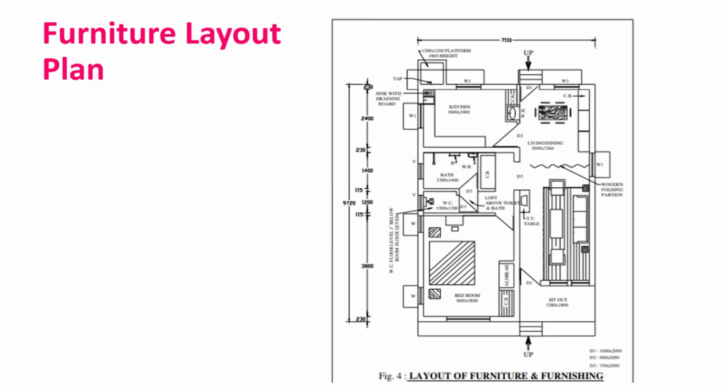Surface water drains. Again, we are required to have any type of land, passage or other area within the curtilage of the building effectively drained by a surface water drain. We have already seen earlier that many times we need to have that sewage plan or this open drain plan also, so that surface water gets drained, that is also required. And again it specifies that the written approval of the authority shall be obtained for connecting any subsoil or surface water drain to a sewer.